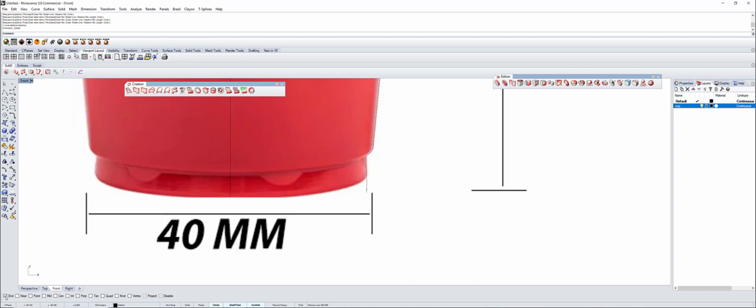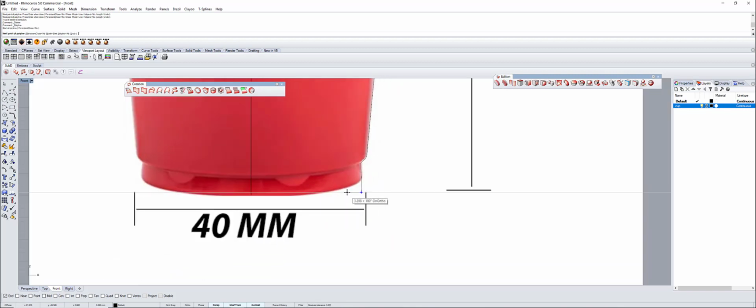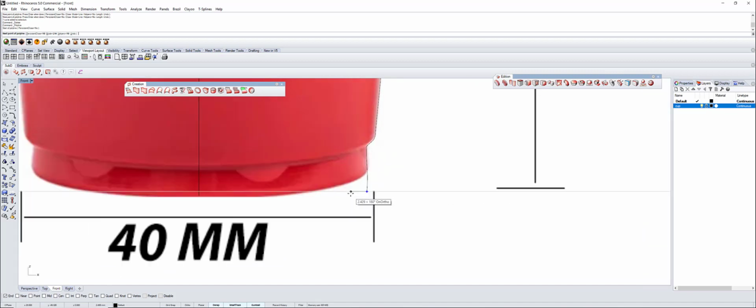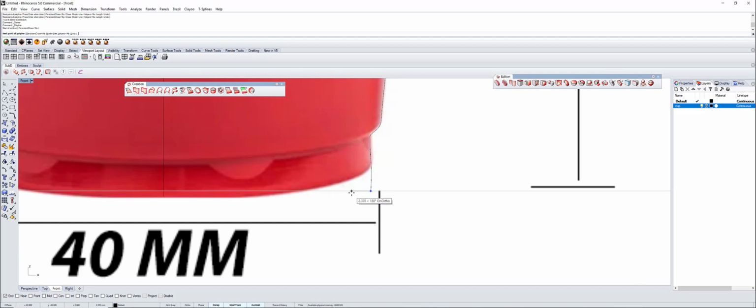So again, enable Ortho, going to this tool. Remember that Rhinoceros always says the last command that you use. So if I press enter, I'm going to call this Polyline tool. There it is. So I click there in the end. This Ortho tool, what it does is put the line straight without using the Shift command. So I'm going to go like minus point 0.7.